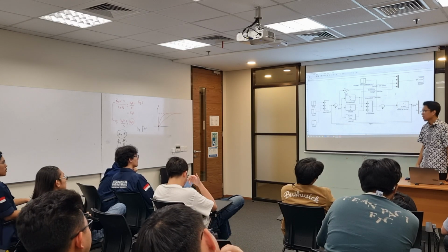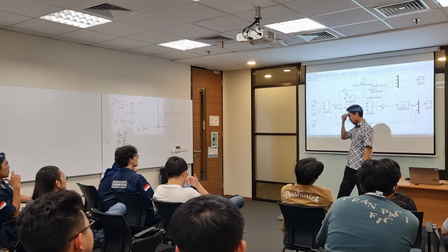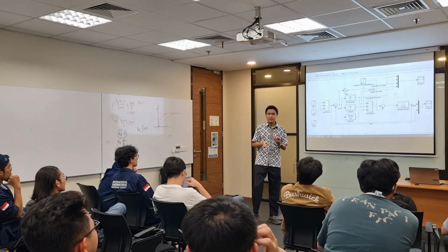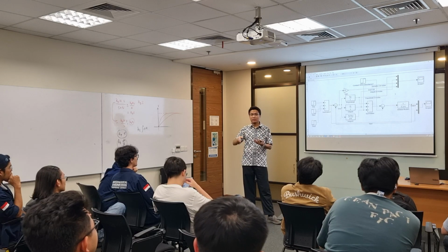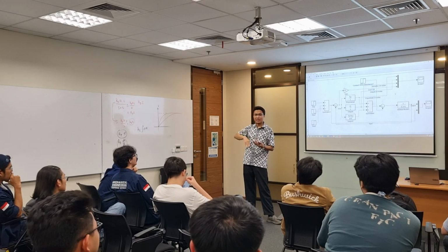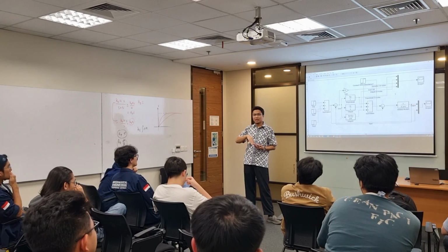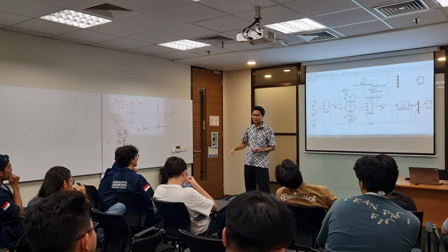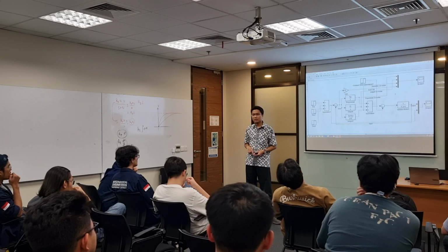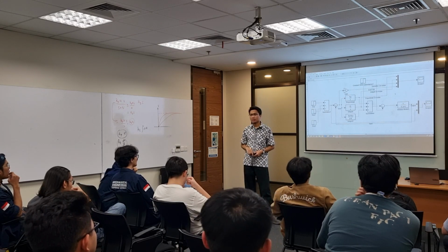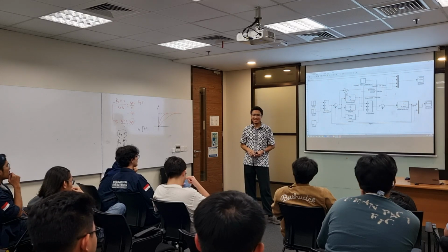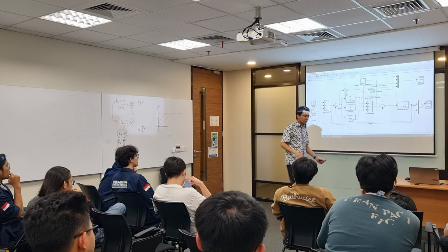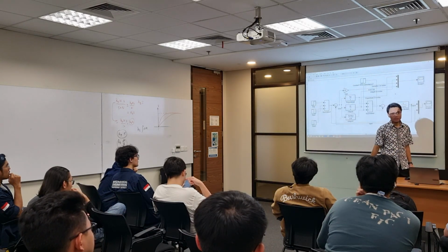The I part, the integral part, you need when you expect your system to have a steady state value. If the input changes randomly like this, integral control is not needed. It's no use. Why is that so? Because the response is very, very slow.